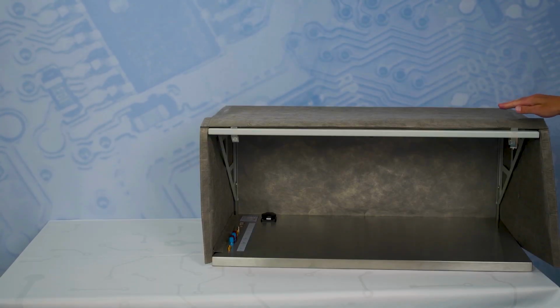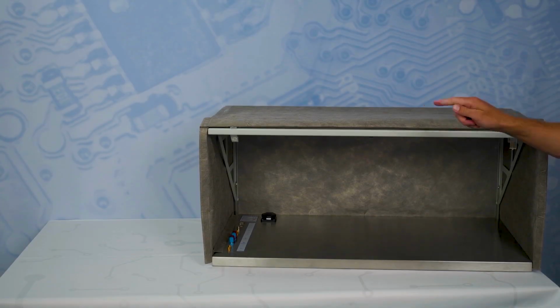Now we have to put the shielding tent over the frame, and to get a good connection between the shielding tent or material and the reference plane, we have here in the side of the tent some magnetic stripes. And you can see here it is very easy to get the connection to the reference plane. On the top side of the frame or of the shielding tent you have two fasteners, and you have to close these.